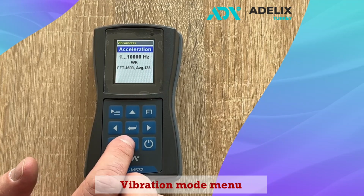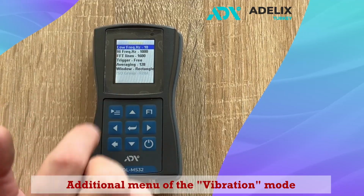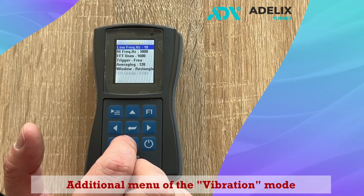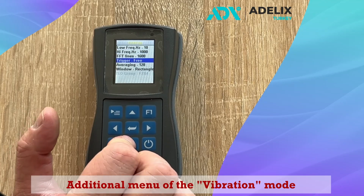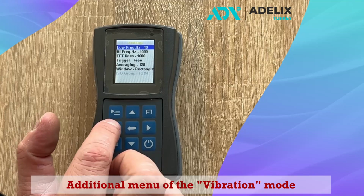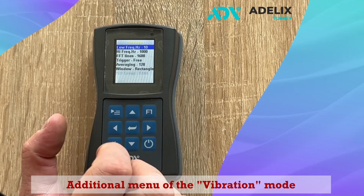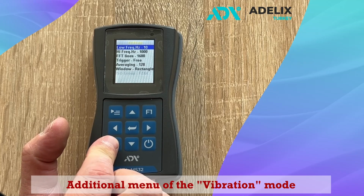By pressing the button on the device, we enter the menu for configuring the vibration speed mode. In the mode settings, we can adjust the frequency range, select the number of lines in the spectrum, choose between a free trigger or a carrier frequency trigger, set the number of averages, and also modify the display mode.